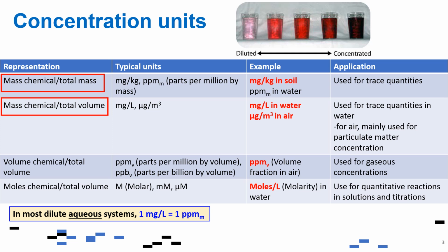For checking the total suspended particulate or TSP in air, a known volume of air sample is passed through a filter, and the change in weight of the filter signifies the accumulation of particles on the filter. And if we divide this one with the total volume of air that passed the filter, we get the microgram per cubic meter concentration.